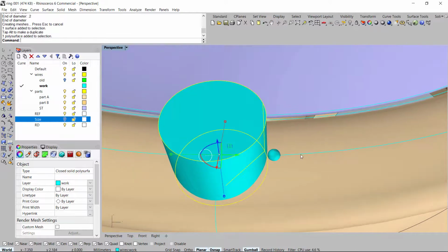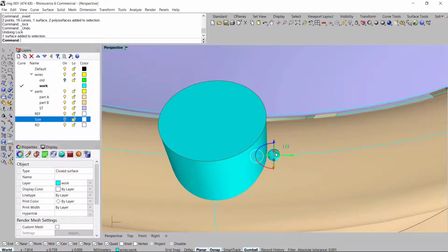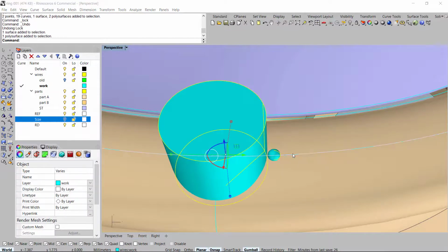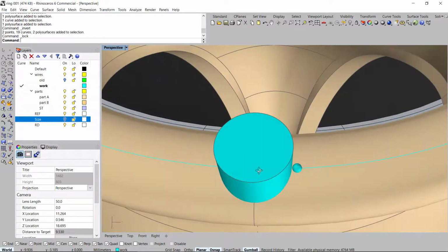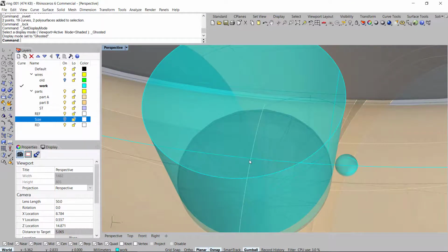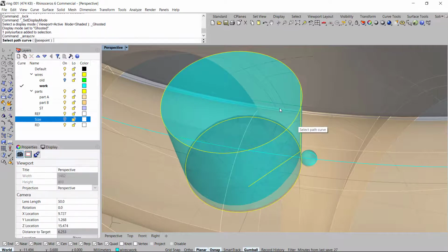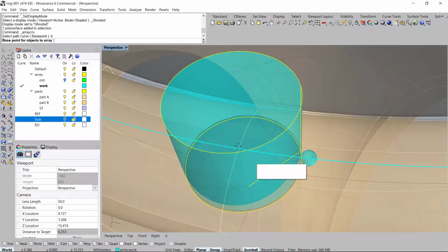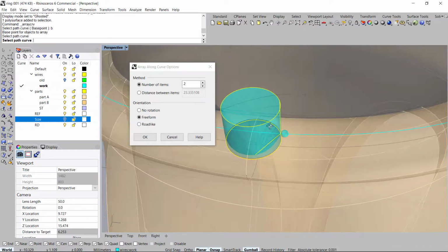Alright, so we'll select this, the body and the curve, lock everything else. Well, we'll minus that. We want to make sure that the guide is selected as well. I'm going to use the Array CRV tool. I'm going to use ghosted so we can actually see the curve right on the inside there. Select the curve, run Array CRV, hit the letter B, right click, and it will select just the quad right there on that curve. Select the curve.